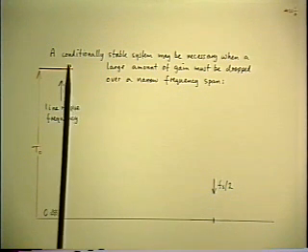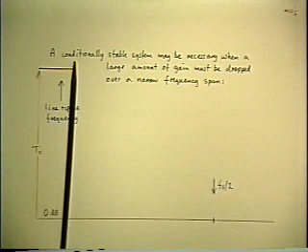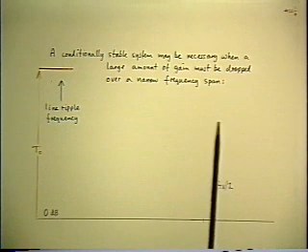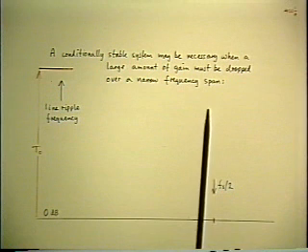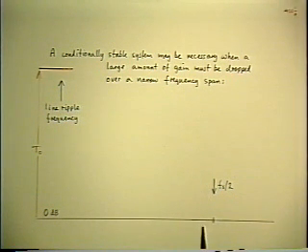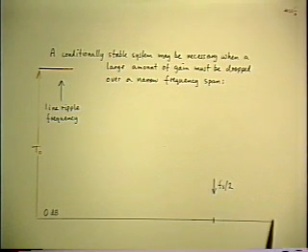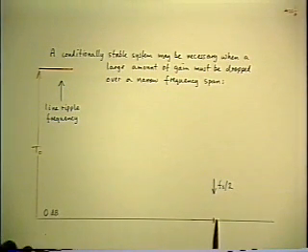So, a window is now defined. The bottom of the window is 20 kilohertz, and I have to keep 40 dB up to that frequency, but I now have to impose another side. I have to impose a maximum frequency at which I can allow crossover to occur in order to keep control, and not have the parasitics take over from my design, where the parasitics are something I can't do anything about. So that defines a window. Call it this frequency here.